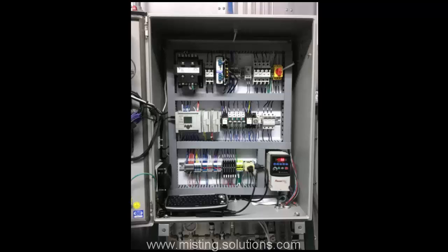Now, there are 2 other signals the Johnson Controls building automation system uses. The first one is a signal to tell the unit to run, or we could call it an enable signal, which is an input signal. The second one is an output signal from this control cabinet, and that is a common alarm relay. Anytime this unit goes into alarm and shuts down, there is a common alarm relay, or a set of contacts that close, that tell the building automation system that this unit has a problem and is shut down.